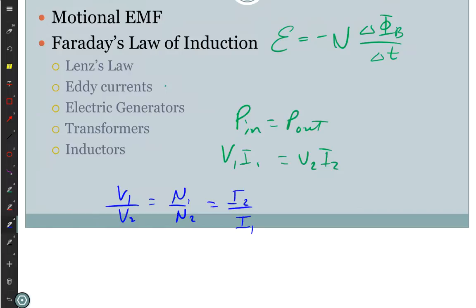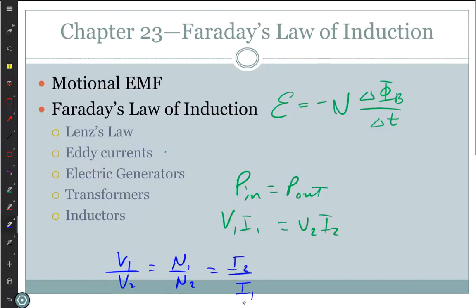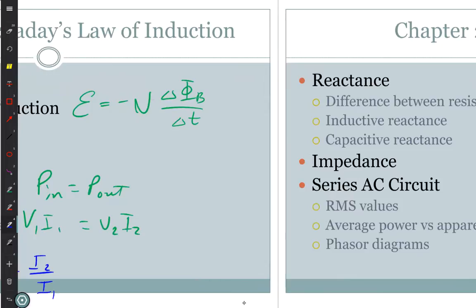Inductance means that you have a magnetic field produced by the first coil, and then that changing magnetic field produces a voltage in the second coil. That's the mutual inductance. An inductor is a self-inductor. You wrap a single wire, you put current through it, the current makes a magnetic field, but the change in magnetic field induces a voltage. And so that's what an inductor is. Same idea as a transformer, except it's just one wire. So make sure you can work with inductors.